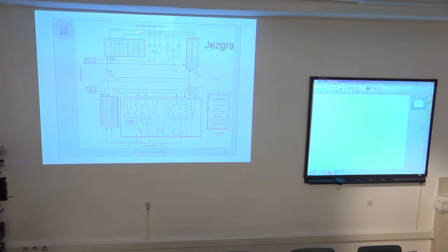M register as a modification register, but it is separated from this I, L, and B because I can combine any M with any of I's. For example, I modify I1 with M2. I modify I3 with M0. Okay? But these three are commonly referenced in the sense that modulus L0 always corresponds to pointer I0.